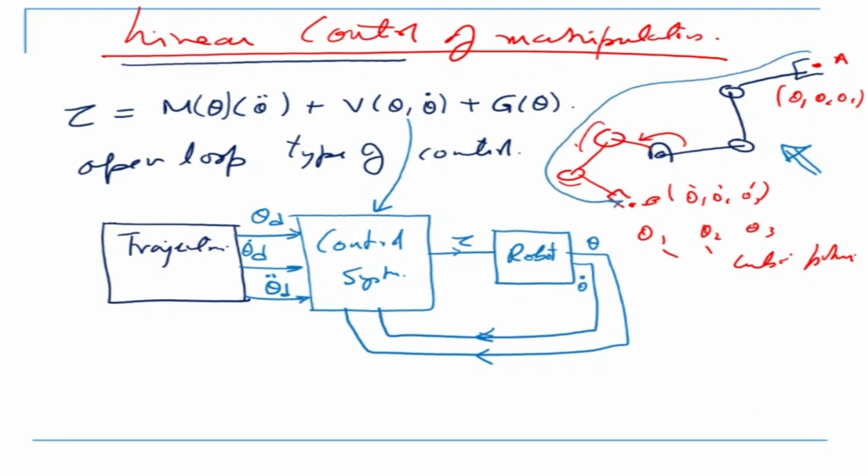The end effector has to move. Now to do that, all the joints will have to move, and we can find what the joint angles are at position A and the joint angles at position B. Then the controller basically has to move the joint angle. So from angle 1 it will go from theta 1 to theta 1 desired. So the controller knows it has to move by this much angle. So it will simply change the angles for theta 1, theta 2 and theta 3 until we have gone to point 2.